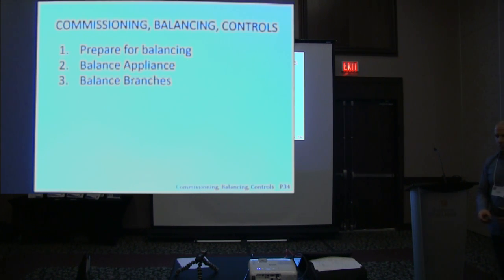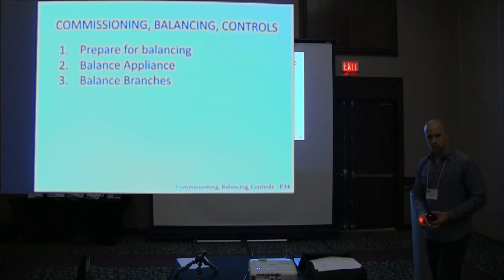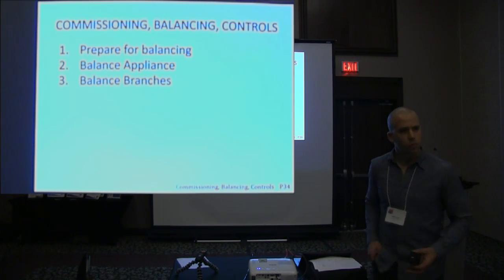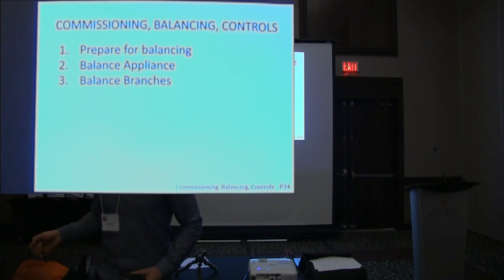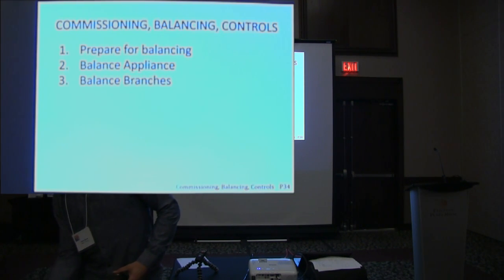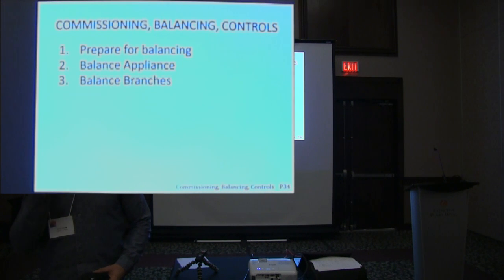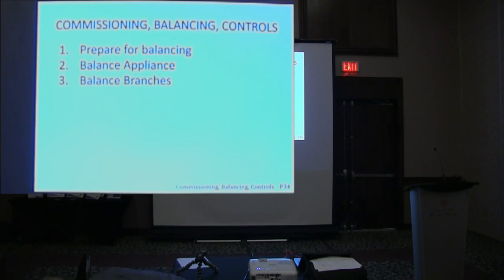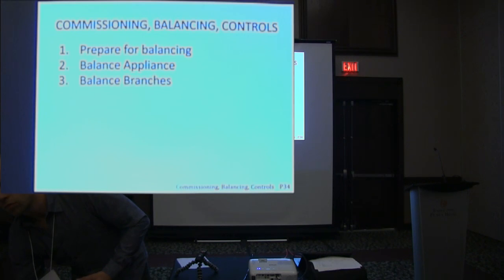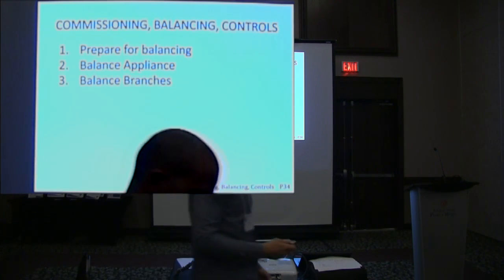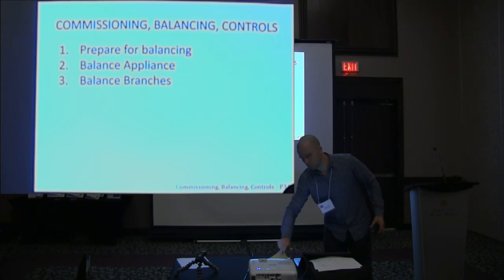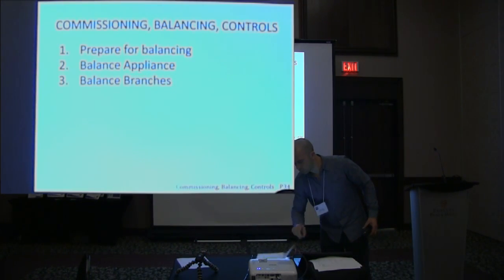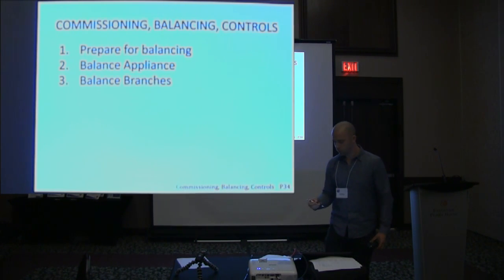The most recent certification checklist document actually asks you to record all the exhaust flows and exhaust regulations, and all the supply flows. The point of the checklist is to really do that field verification, typically done by a third party or the installer. It's a step in actual documentation of the flows and how the system balances.